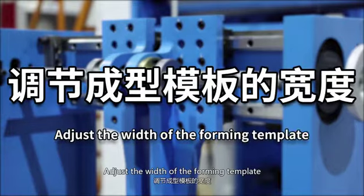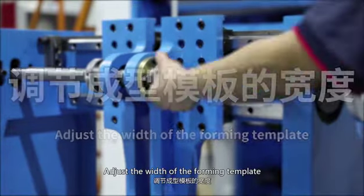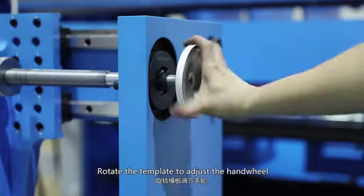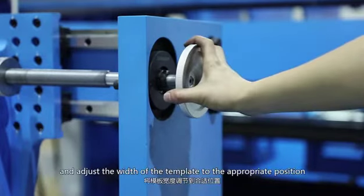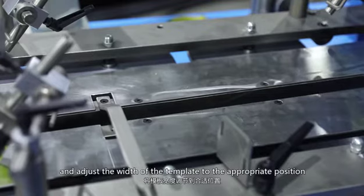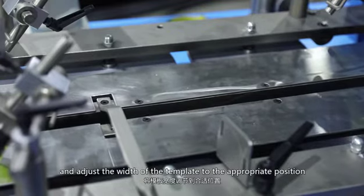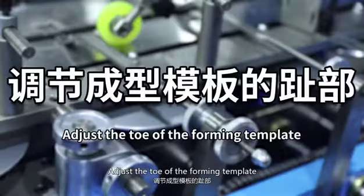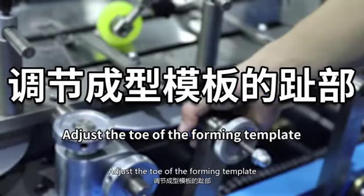Adjust the width of the forming template. Loosen the fixed hand wheel. Rotate the template to adjust the hand wheel and adjust the width of the template to the appropriate position. Lock fixed hand wheel. Adjust the toe of the forming template.